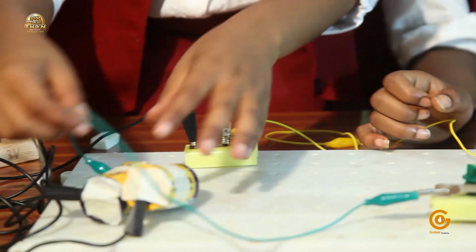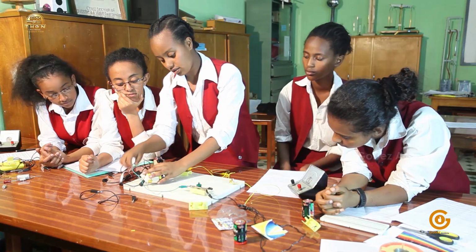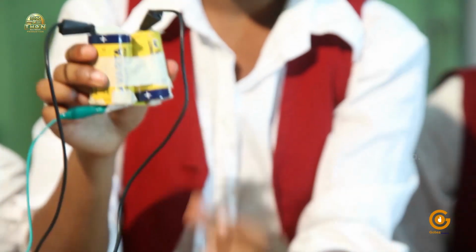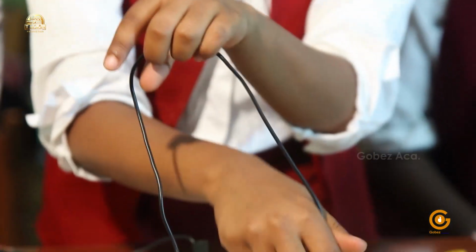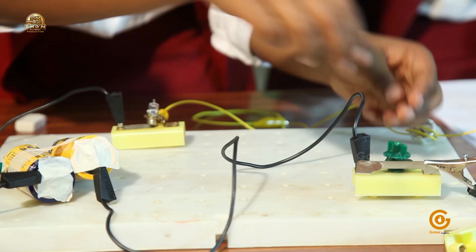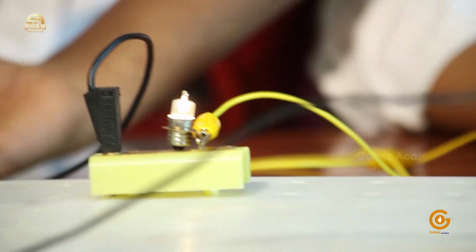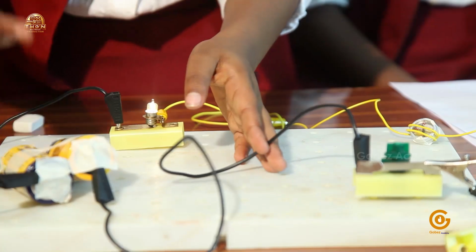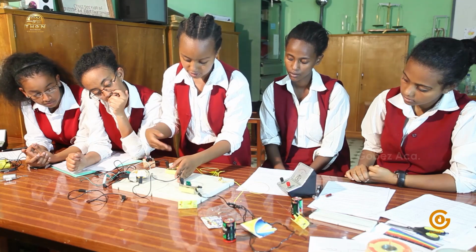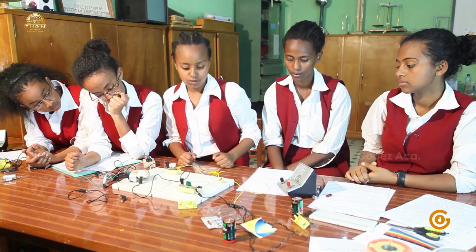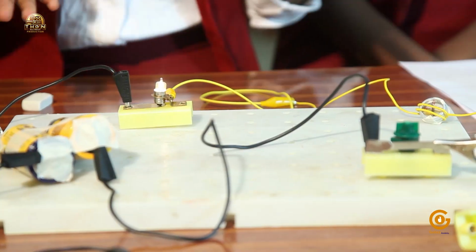By using the second wire, we can use 3 volts by using both of the dry cells. And we can see that the deflection is really big, because we have used a stronger supply, and the current in the circuit also increases. So we can see that the galvanoscope also measures the amount of current.